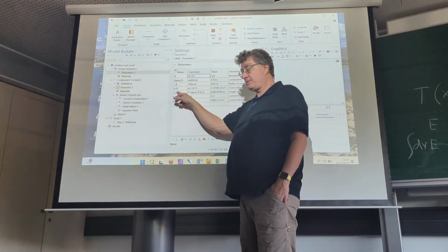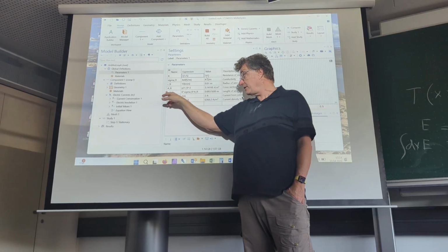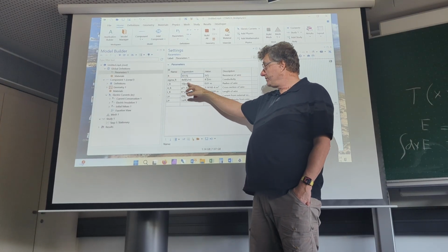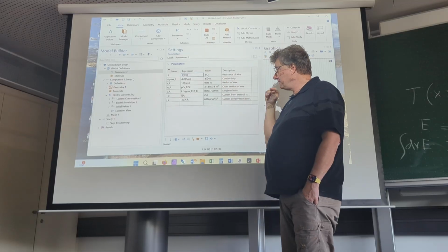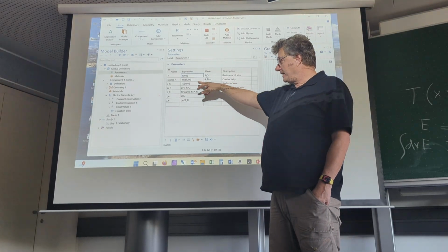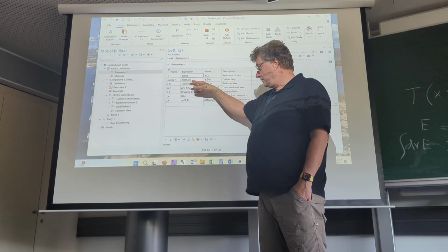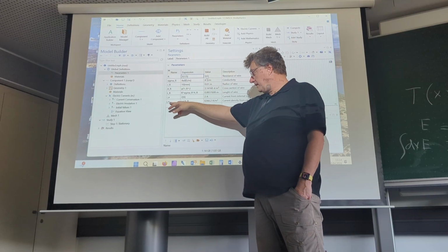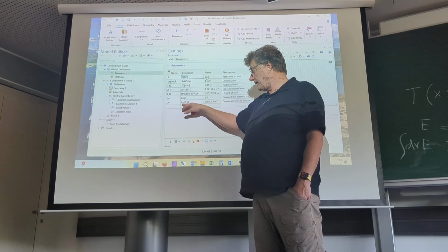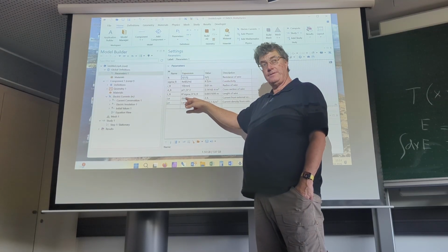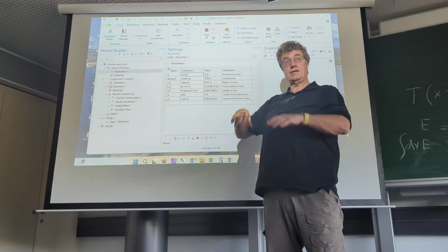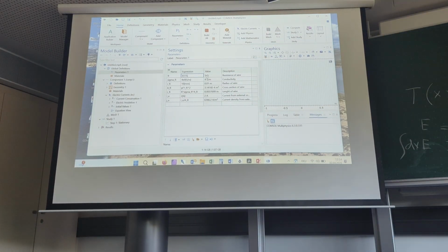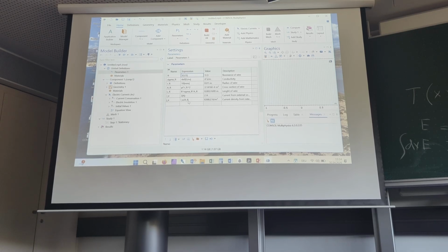I calculated the length according to that equation. I just resolved for the length of the resistance with the given sigma, the conductivity, and a given radius for the wire. And here I calculate the current density. I run 2 amps through it, but I divide by the cross section. Why do I do it? Because the program later wants a current density for configuring the current source. That's why I already calculate it. So I hope these equations make sense.